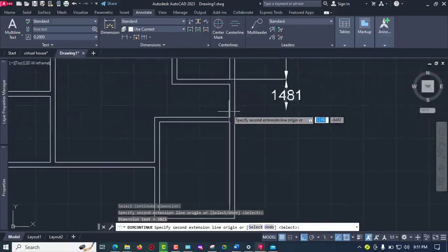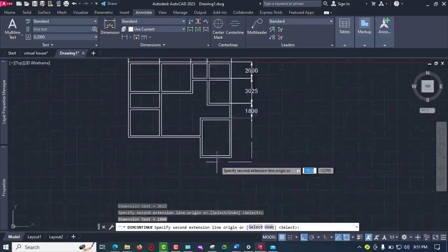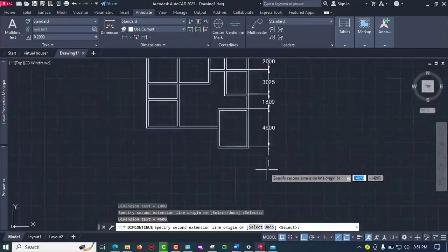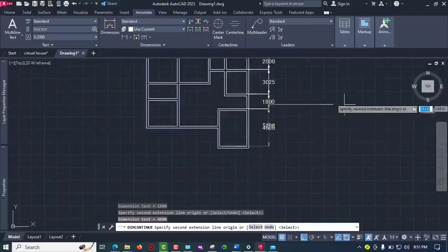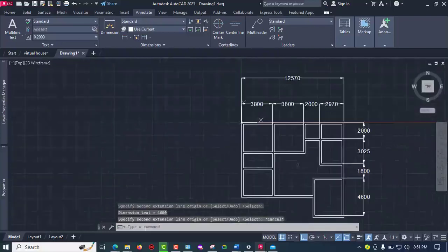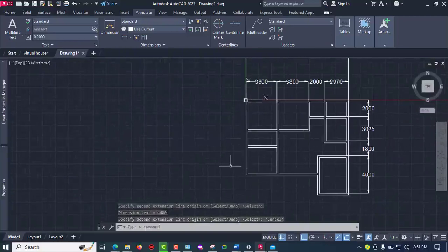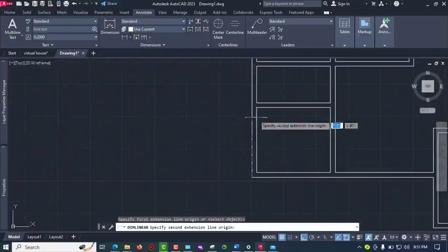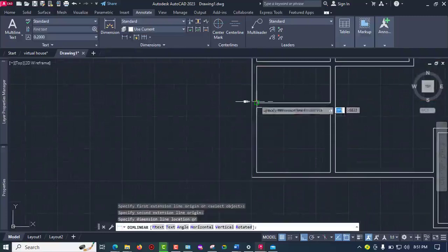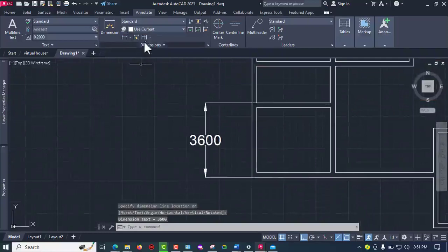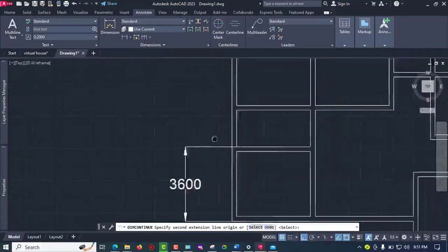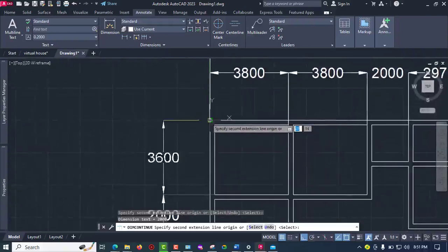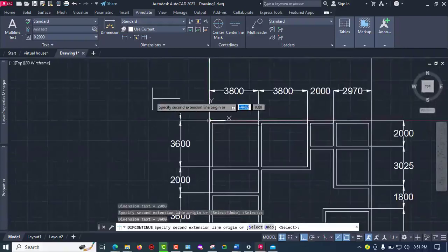Just click points instead of stressing myself. So I don't need to click on the dimension tool over and over again like I did in the previous example. The moment I click on the dimension tool, click this point and this other point, move here, what I need to do is click on continuous dimension, and it automatically starts dimensioning continuously. Then you hit escape to leave.